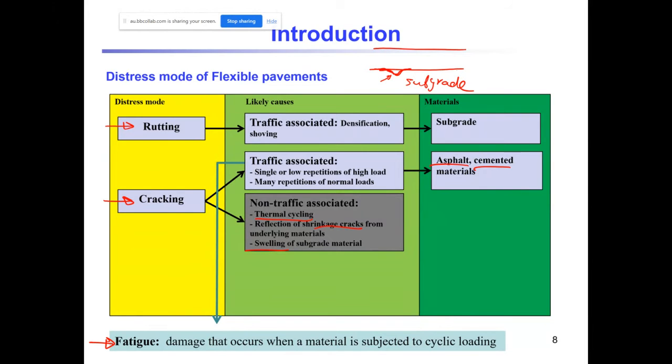And that is mainly the case when you are dealing with swelling soil, reactive soil. For example, in Western Sydney, we have this type of material. We are dealing with reactive soil. If you add water to it, it will expand. During the dry season, it will shrink. And this level of deformation is considerable and can cause failure of the road.